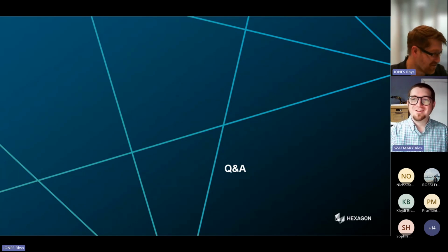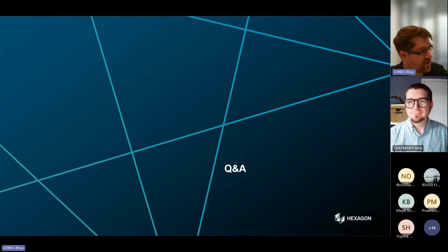It's not general FE stuff. It does produce the super element for you. Oh, okay, great. So you connect up everything within there, and there's just a button which says condense, which is our word for create the super element. You press it, and it does all the condensation for you, and then you can use it within your Romax model. So it's all entirely within the software. You can use other super elements from Nastran if you've created them already, then you can import those as well. But yes, you can do it within Romax.